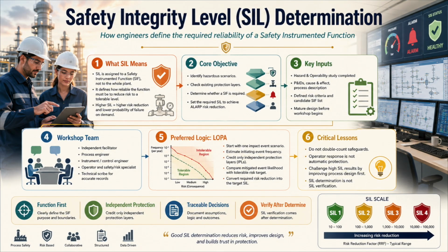The team must be multidisciplinary. You need process knowledge, operating experience, instrumentation and control competence, safety and risk expertise, project understanding and facilitation discipline. An experienced operator is essential because drawings describe intended operation, while operators understand actual operating behavior, abnormal conditions, startup difficulties, bypass practices, and the time realistically available for intervention.